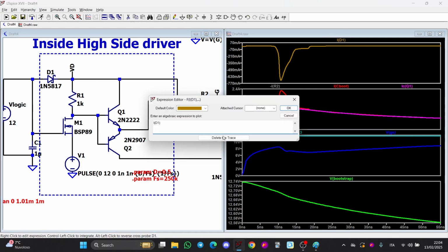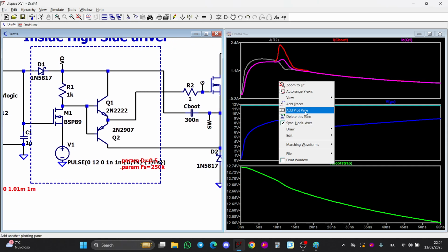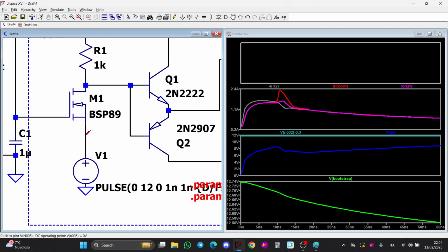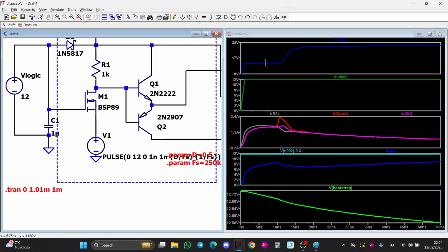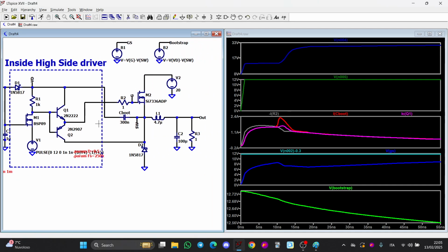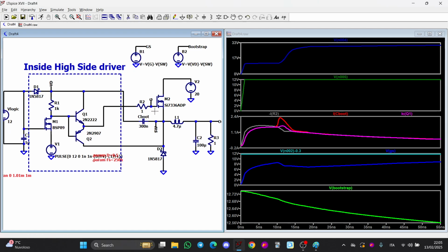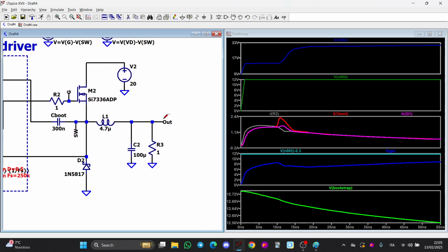But anyway, so we are now seeing all the flow of the current and how the Bootstrap works. Now, regarding the voltage, this is our waveform, and what we have here is the same waveform turned up, because of course the Bootstrap is a way to level shift your waveform. Now, does your Bootstrap impact the output voltage? Yes, but not so much.